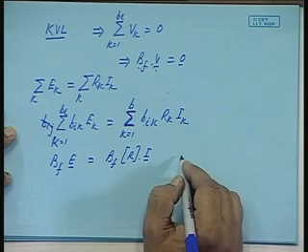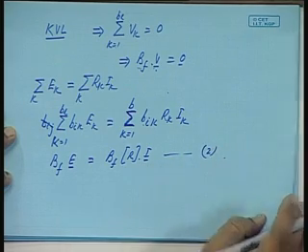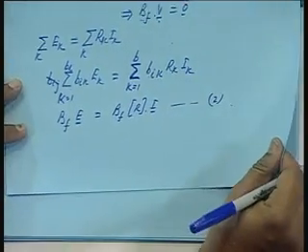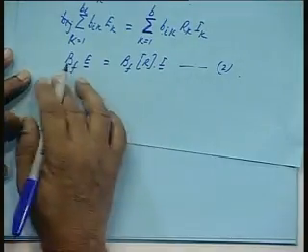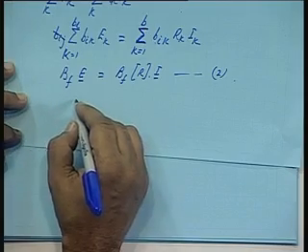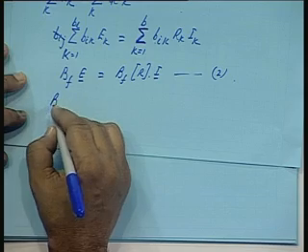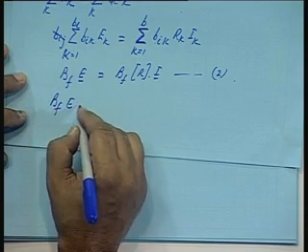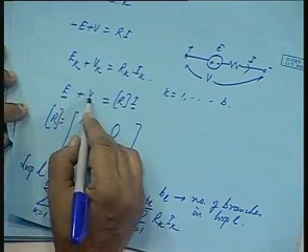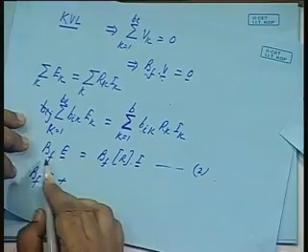This is a very important equation that we get in terms of the loop matrix Bf. Now, this we could have got from the other equation also. If you would have multiplied E plus V equal to RI by Bf, and Bf into V is equal to 0, that we have already seen, we could have got the same relation.